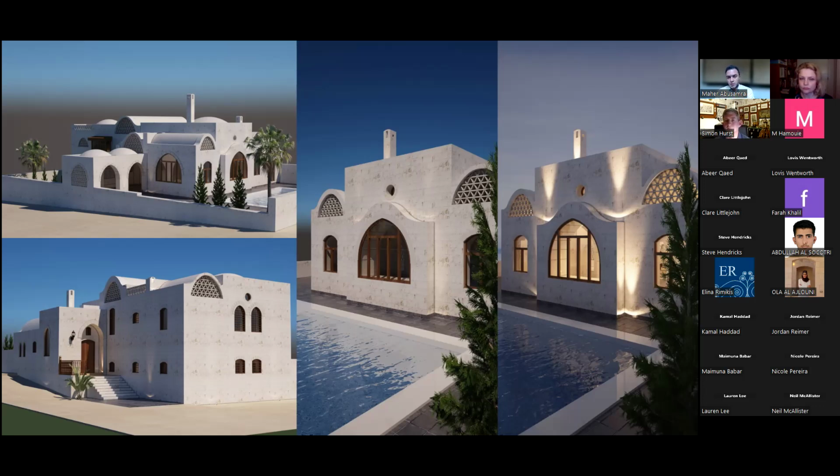But that calculation is comparing only the material and the thickness of the material. They are not taking into consideration the height of, let's say, this dome or this room, 10 meters, with 16 windows openable at the top, so the hot air can go out and you have ventilation. They don't have, in the system or the software itself, these ventilation factors to take into consideration. So we have to try it after we finish that project.